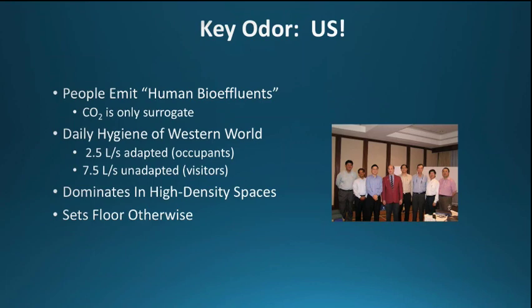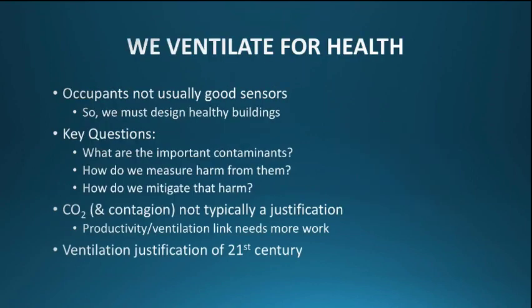satisfied from human bioeffluents. And these kinds of numbers are going to dominate in high density spaces where there's a lot of people, auditoria, that sort of thing, and probably that much ventilation will take care of everything else too. But if you're in a low density space where there aren't very many people, then these numbers are floors, but we may have other reasons to ventilate as well. And of course, the one that's of most interest these days is health. We're trying to raise the standard of living, and health is very important.